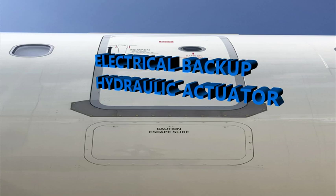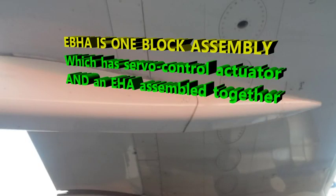And just a little bit on the spoiler number 5 pair. It's using a servo control actuator. It's a mixture of a hydraulic actuator, because you have electrohydrostatic, as well as it being a servo control actuator, and they're just put together essentially in one place architecturally. And it also has a power electronic unit to it.